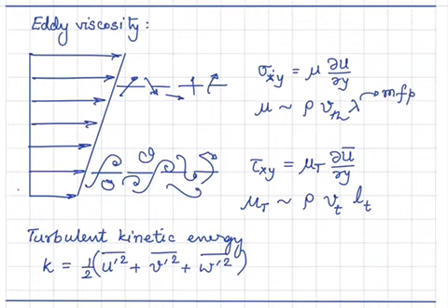It's very similar to any kinetic energy we define using velocities, but it's defined per unit mass. So that's where the rho or mass m does not come in. If you think about this quantity, half of u prime square, v prime square, w prime square, it's also like the resultant velocity that you can get at any point.